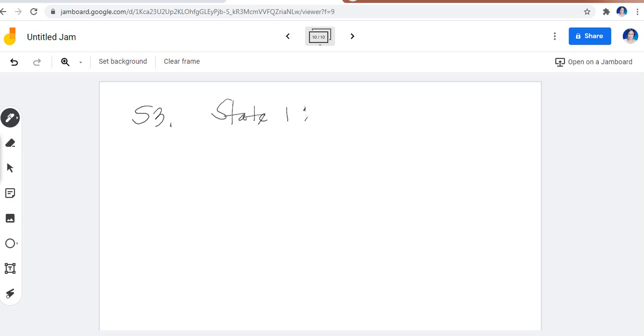In state 1, you have the humid volume or the specific volume, 13.28 cubic feet per pound mass, and you have the humidity, which is 0.00867 pound per pound mass.